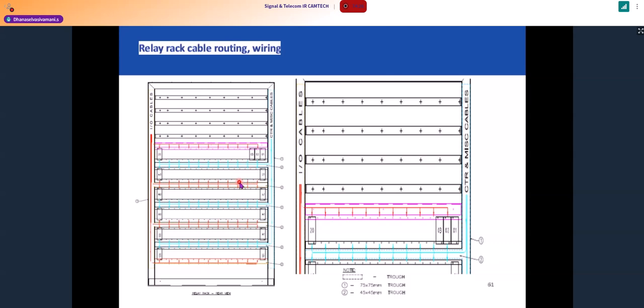And one more request regarding the fire heat sensing cable: we are not recommending using heat sensing cable either in our KFA BMC rack or EA rack. If at all you want to use it, you can use it in the CT trough. The CT trough is there, no? In that trough you can use it. In any case, you should not mix it with our EA supply, since the heat sensing system uses an external 24 volt, which is not a clean supply, and all our supplies are clean. That mismatch will lead to system failure. That has happened in a couple of stations now.